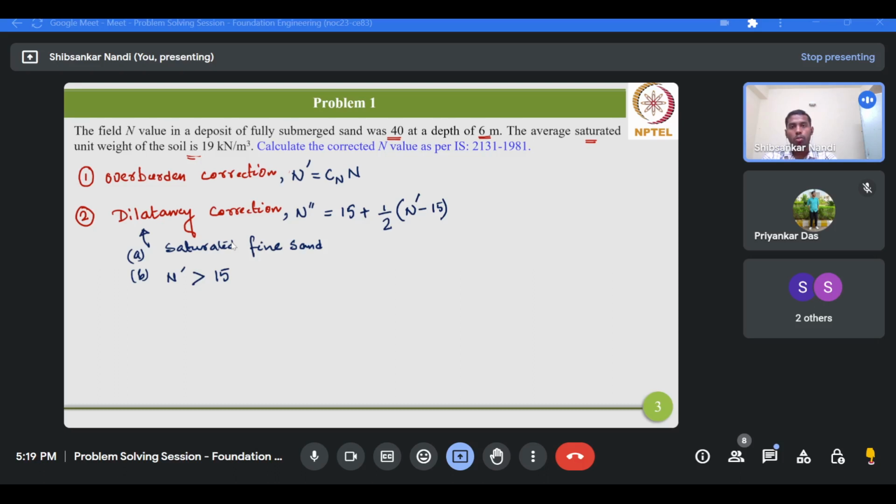The depth which you are considering, multiplied by the unit weight of the sample, will give you the overburden. Though effective overburden is a different scenario that we'll discuss. As you go down from the ground surface, your overburden will increase, which means the confining pressure is also increasing.